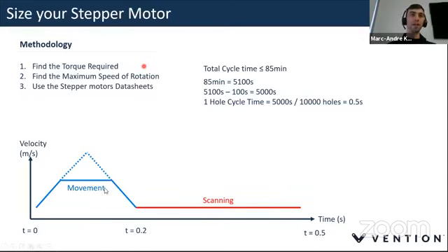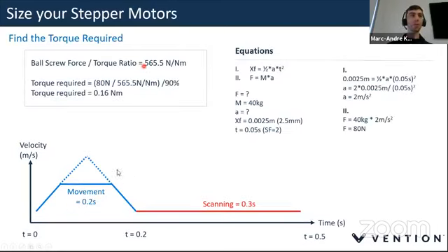And what we will do is make it more simple, because if we have this cruising speed and acceleration, deceleration, it might be hard to find out how much time is going to be spent accelerating, decelerating. So we'll make your life easier. Why don't we make it accelerate up to half of it and decelerate for the other half. So that gives us 100 milliseconds to accelerate from here to there. So it's going to be half the distance to carry that job. And so it gives us more information.